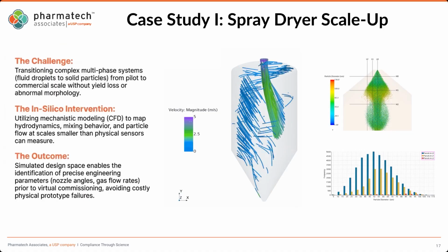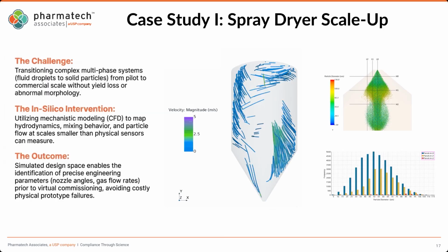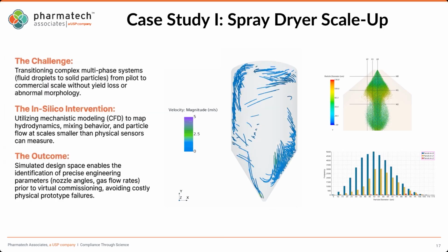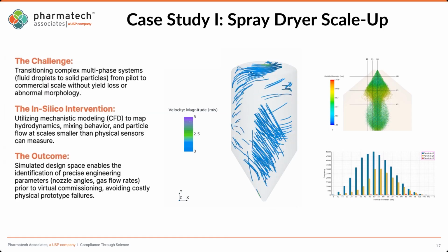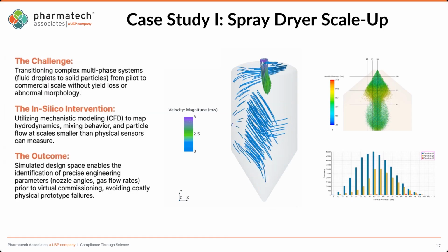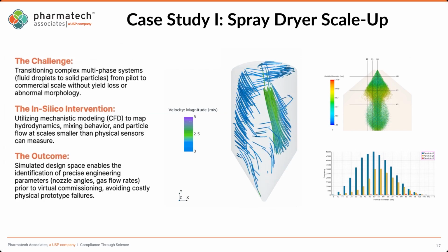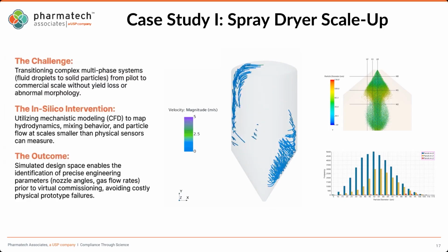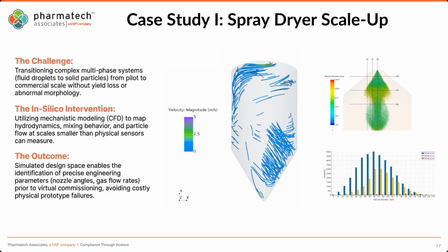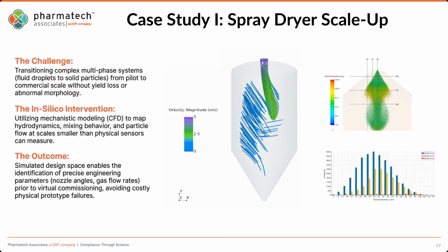Spray drying is a very complex process, especially when we go to a different product, let's say an inhalation product with an amorphous dispersion. The properties of the product produced from spray drying impact the drug delivery. If we go to larger particles, the particle is going to hit the back of the throat of the patient. It doesn't go to the lungs. If we go to very small particles, they would go to the alveoli versus the bronchi, and we become toxic.